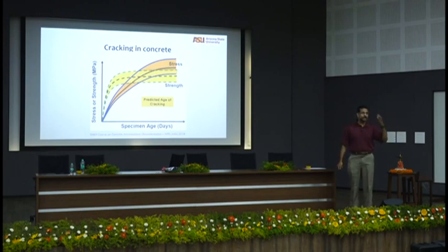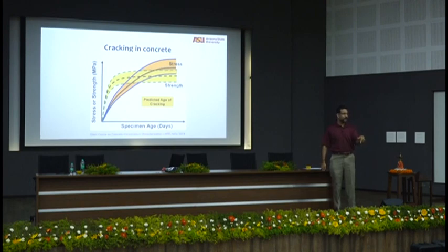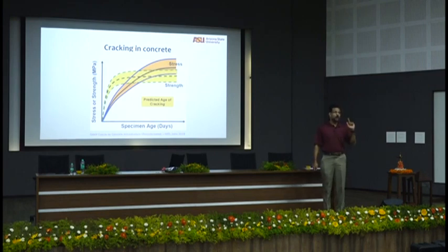And we see that all the time. How do I control cracking in concrete? You don't have to control all the cracking in concrete. It's a natural reaction. Let it crack a little. Sometimes cracking a little is actually good. And cracking a little early sometimes is actually good because it can self-heal. But you should know how much of cracking you can afford to. Not all.